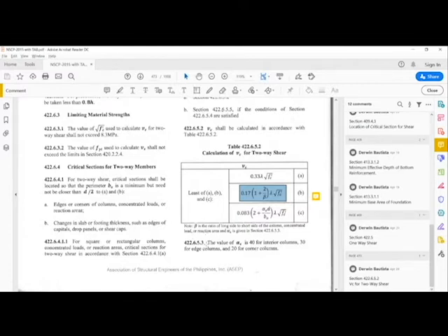If our column, no, is an interior column, meaning to say it's inside your footing, alpha S is equal to 40. If it's an edge column, meaning to say one face is on the edge, we use the value of 30. While if it's a corner column, meaning to say two sides of it are on the edge, no, we use the value 20. Okay, for formula C.